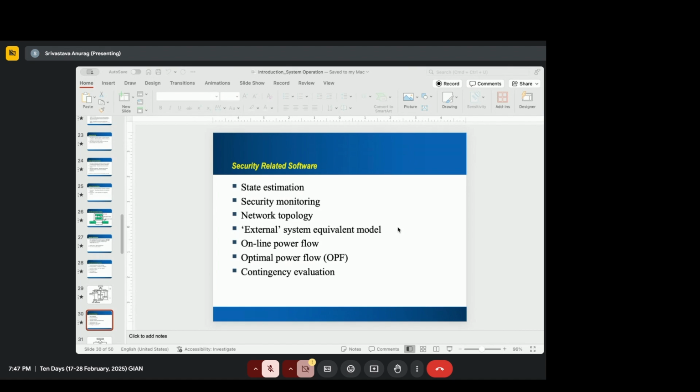Now if you're solving dynamic state estimation, which is a different thing, which is typically done with PMU measurement and requires fewer iterations to solve, that will require you to solve in a few milliseconds and more often, right? So state estimation is the way you would define the real time. If there is no software, if there is no analysis which needs a result of state estimation faster than 30 seconds, then 30 seconds becomes the real time requirement.